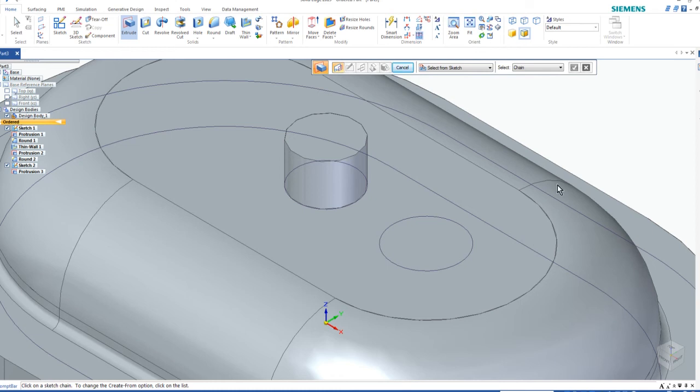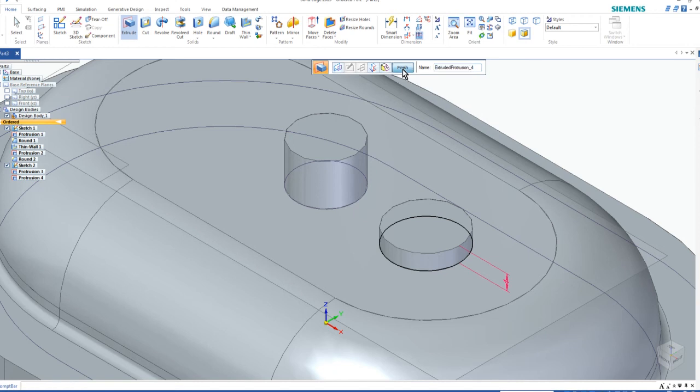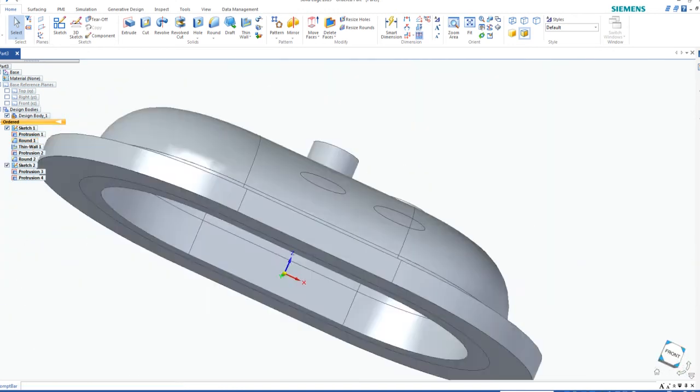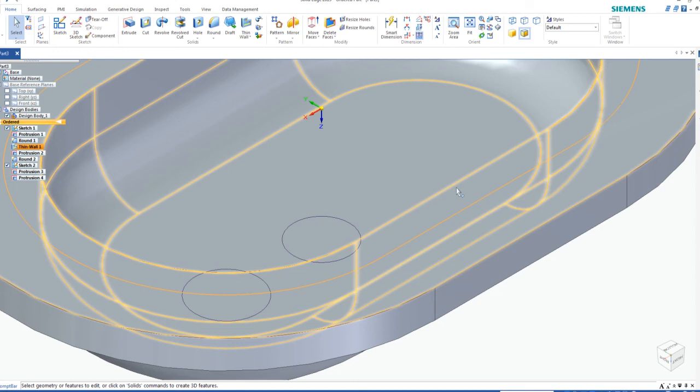Now the second one, which we can select, accept, is going to be 4. So we're going to type in 4, enter, and pick anywhere in space. Let's finish our sketch and cancel. Let's quickly take a look. This one comes up 11, but it also goes down a total of 8 into the cavity. So it has to go a total of 8 into this cavity.